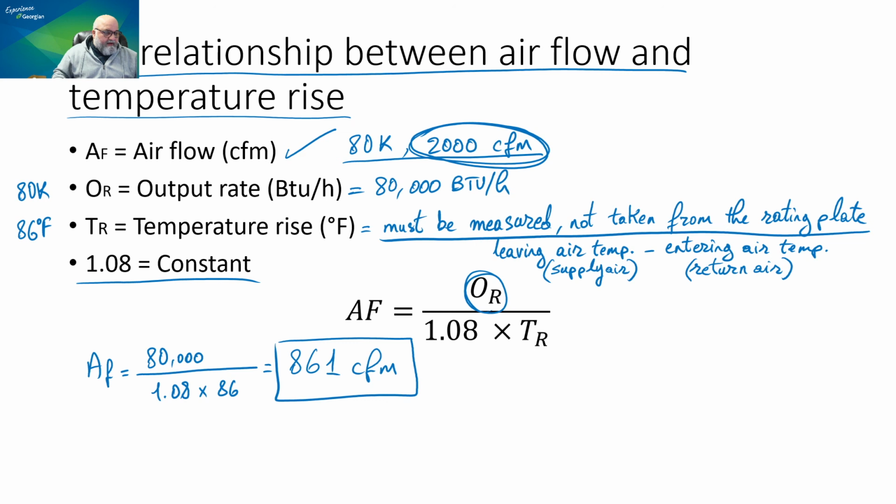Oh, so I have a question asking whether low CFM can be an indication that the motor capacitor is bad. If it has a running capacitor, yes, but not this bad. This disparity between 2000 and 861 indicates more than just a motor capacitor. It can indicate closed air passages and a dirty filter or dirty air coil.